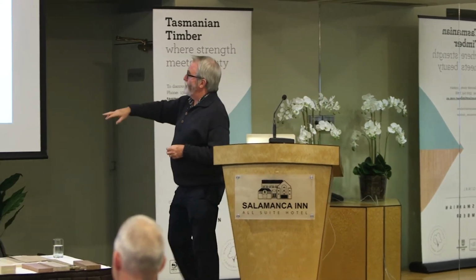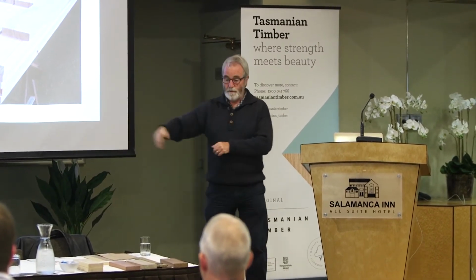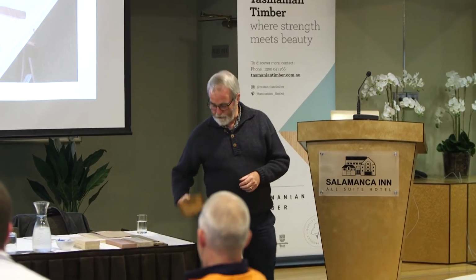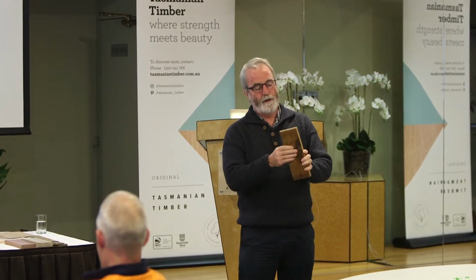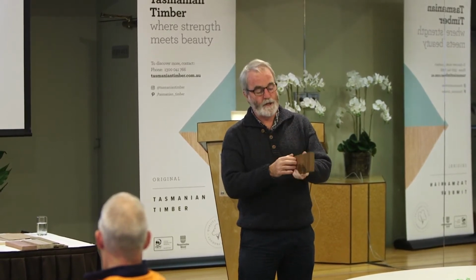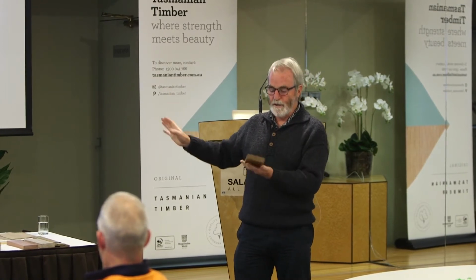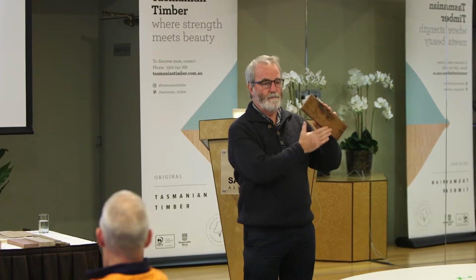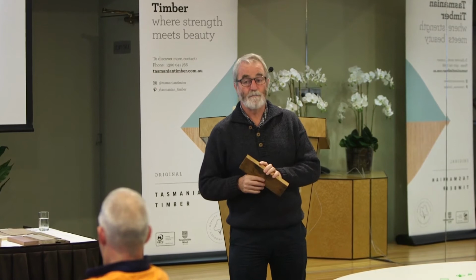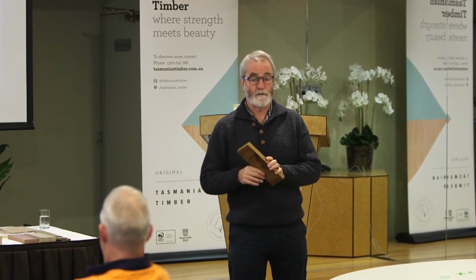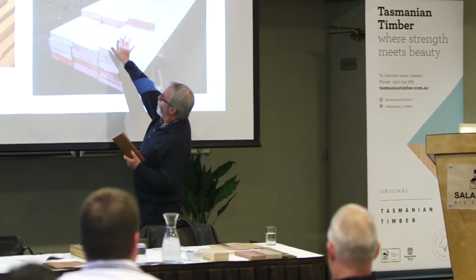So this is board, kiln dried, standard moisture content. It's rough sawn. It's a bit like the back of all these boards I've shown you. It's come off the saw, it's been racked, it's been dried, it's been reconditioned, put in the kiln. It's probably somewhere between 11 and 12% moisture content, but it's that shape. And that's then a perfect blank to be used by somebody else to make something relatively glorious. So these are quite large sections, ready for use.